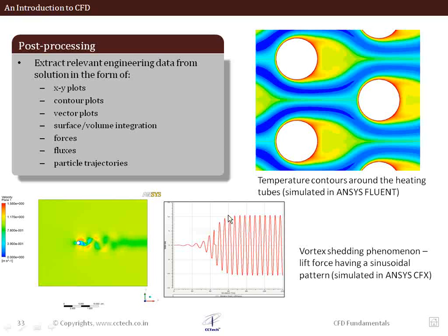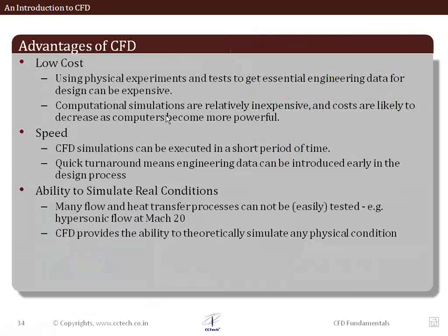You can see the lift force variation with time. This is simulation time on the x-axis, and we have the lift force on the y-axis. It has a clearly sinusoidal behavior. So you can perform such very nice post-processing in CFD tools which are available.